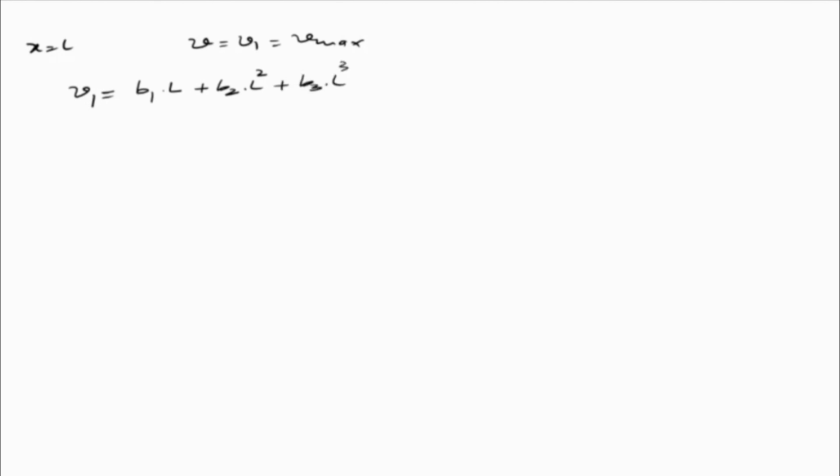So this is the V1 expression. Once again I need to get the values of B1, B2, B3, so that I will get the value of V1. But I have one more boundary condition. Using that boundary condition, I can eliminate another constant also. What is that boundary condition? When x is equal to 0, my slope is 0. Correct, no? In a cantilever beam,